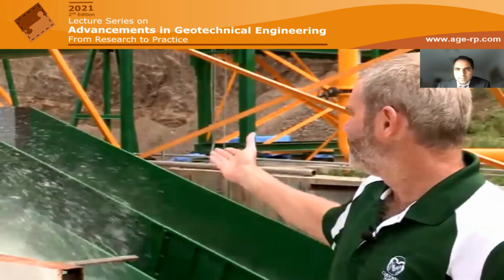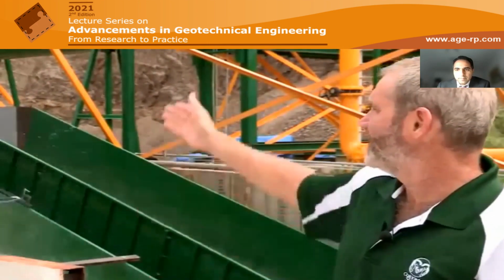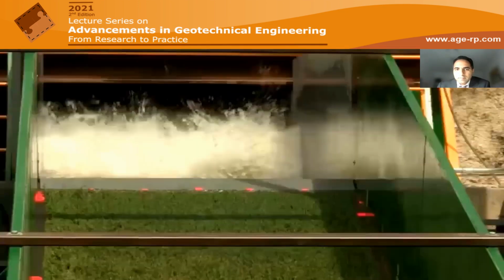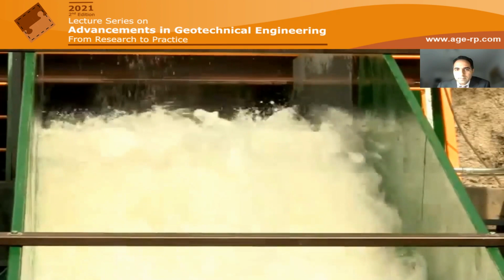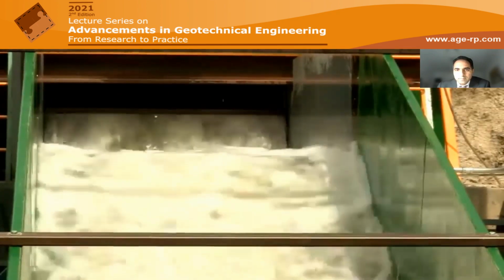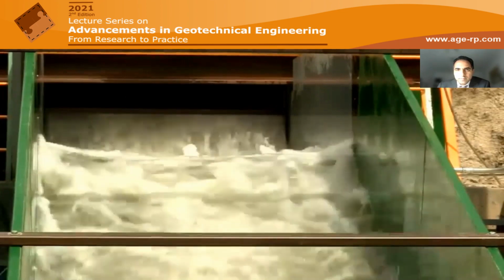What we do is, through the tank, the green tank that we have above us, hold a volume of water. So we release that volume of water at a given rate for a given period of time so that we can simulate the waves crashing over the top crest of a levee and then accelerating down the backside.